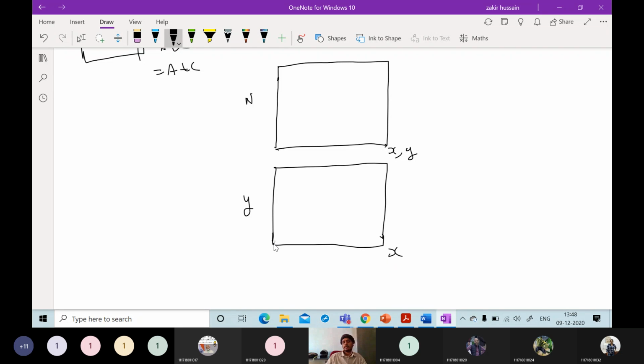So when you draw the first one, since this is a distribution curve or we can say equilibrium curve, this is a diagonal line or 45 degrees diagonal line we can say. Then the x versus y curve is coming like this. So this will be x versus y. Then after drawing n versus xy, first you have to draw n versus y. So this is going to come like this, as in the previous case. So this is n versus y.